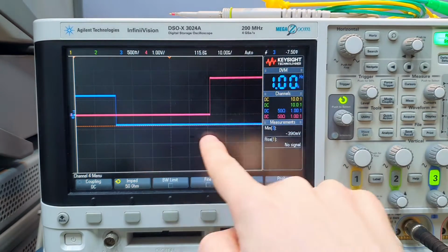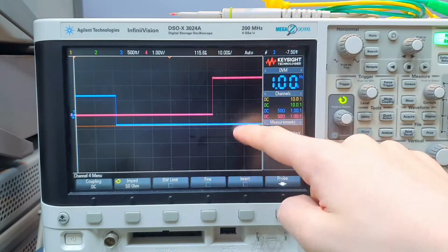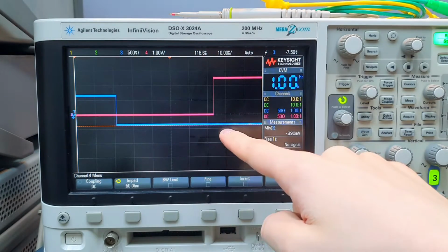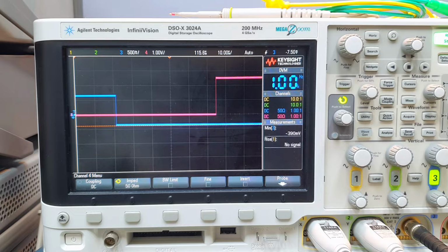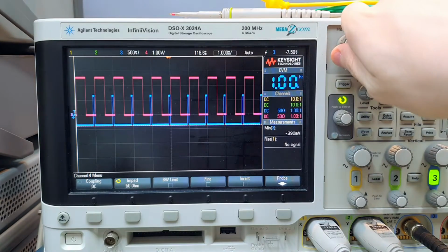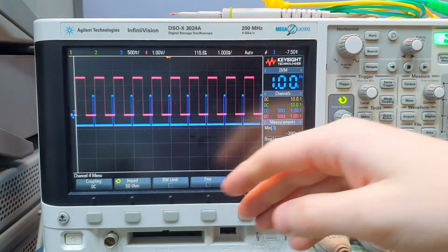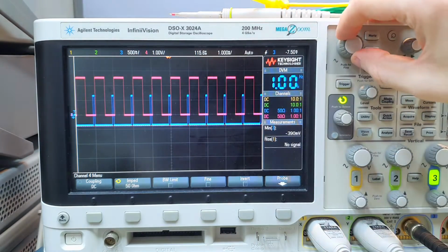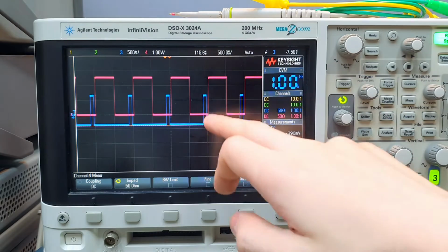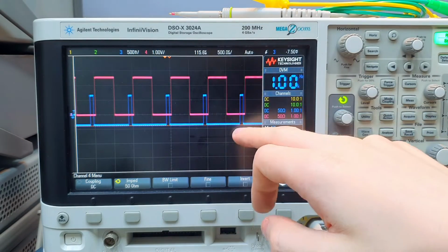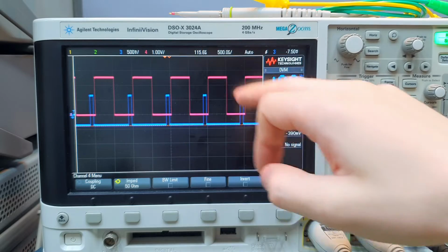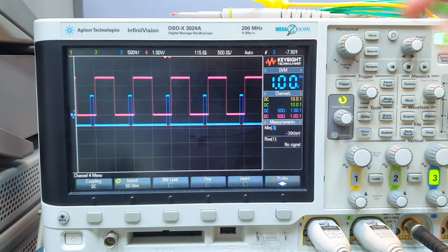that, look at this. Of course, the signals are not synchronized because we have two different time bases, one inside of each Tektronix signal generator. So signals look good here, but of course this is not useful for the measurement setup, as actually in practice we have different frequencies, they are not exactly the same, and the phase is being shifted by this offset of frequency.